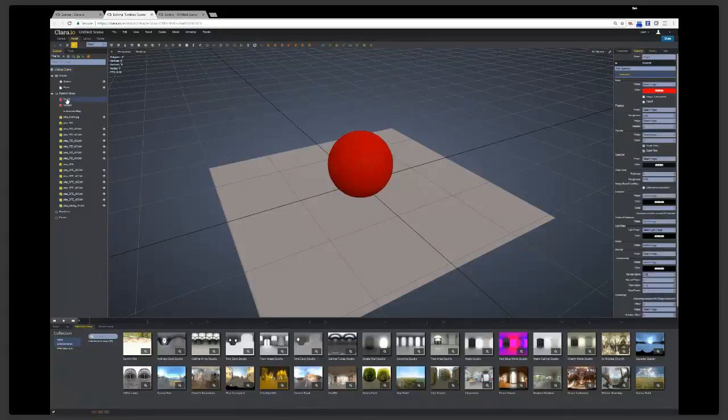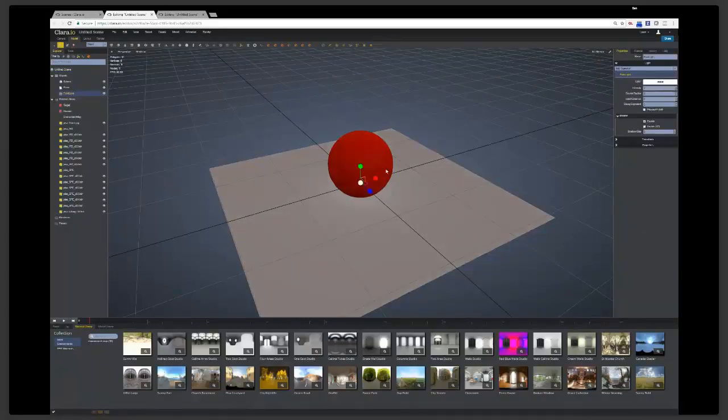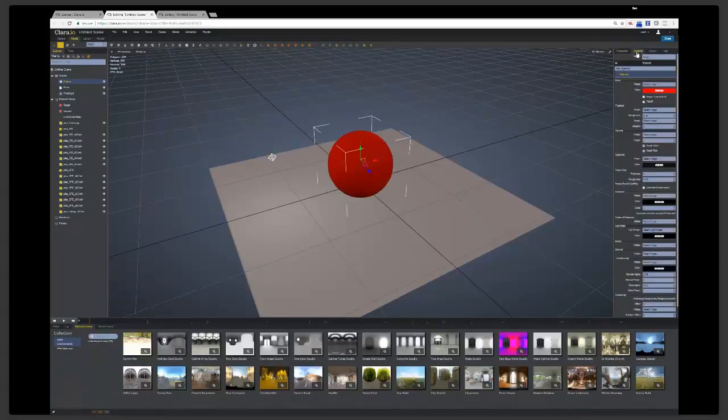it's going to be much more obvious what is happening, because I have a rich lighting environment. I might also add a point light to give you a comparison. We're going to put a point light over here. We probably should default to this, but I recommend having physical falloff. Everything should be physical, and then you'll get much more realistic results. So let's go back to this object. Now that I have a lighting environment, I can change the material properties and see that reflected in real time in a meaningful way.